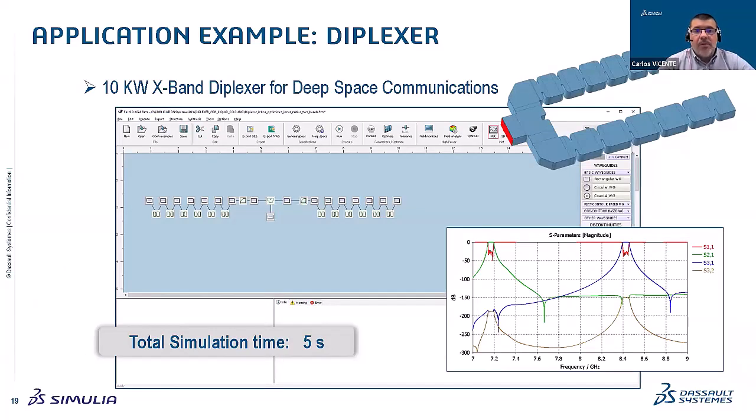We are talking here about 200 or 300 frequency points. So each iteration would be at maximum just 5 seconds. As I explained before, if you are optimizing just one building block like the T-junction, then the simulation time would be lower. But it is just for you to understand the range of the simulation time we are talking about here.